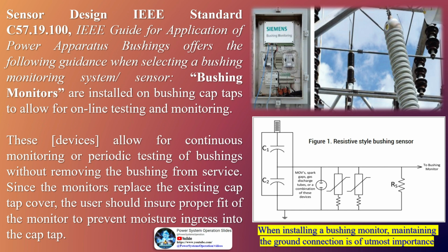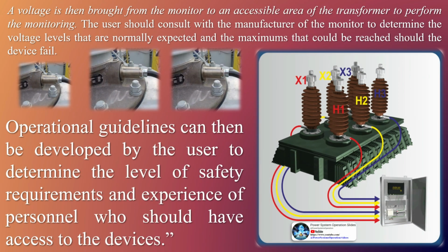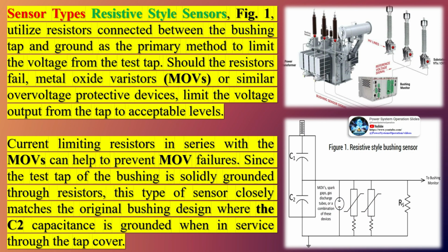Bushings are accessories used in high-voltage equipment for the purpose of providing safe passage for electric current from the external environment to the interior of the equipment, as well as providing the necessary insulation in relation to the casing of the equipment. A few of the more common examples can be found on power transformers, shunt reactors and high-voltage circuit breakers. Despite being accessory to the different equipment types mentioned, and in general being of much lower unit cost as compared to the overall cost of the equipment, bushings perform a function that is essential in operating the equipment. On the other hand, bushings are subject to considerable dielectric strains, and a failure in their insulation may result not only in damage to the bushing itself, but also to the entire equipment to which it is associated.